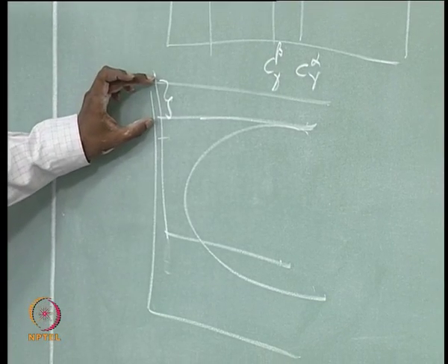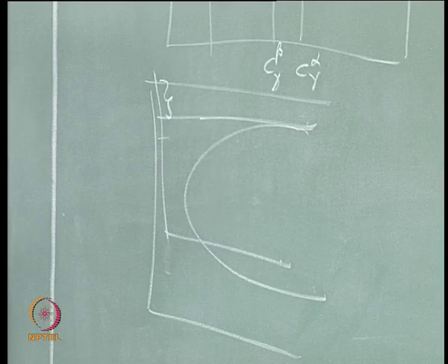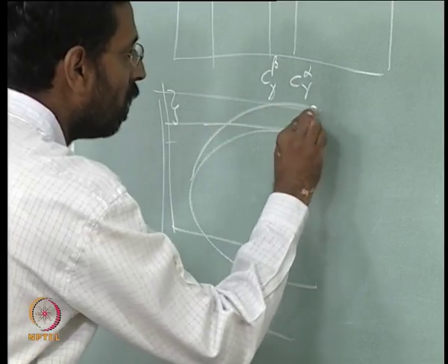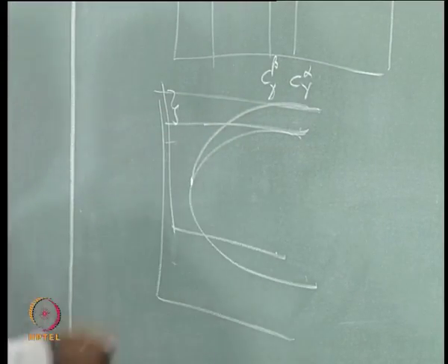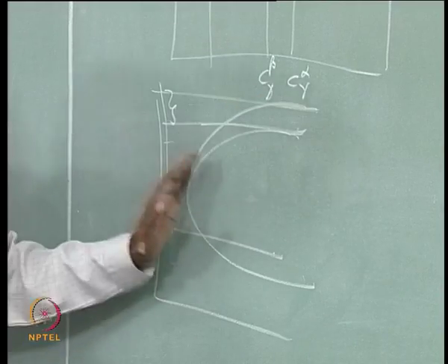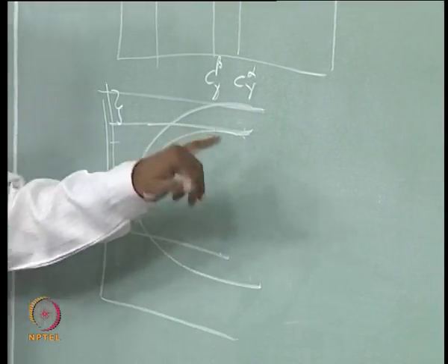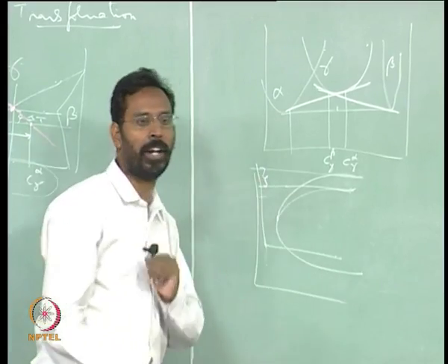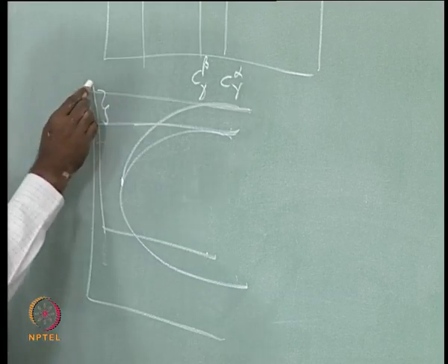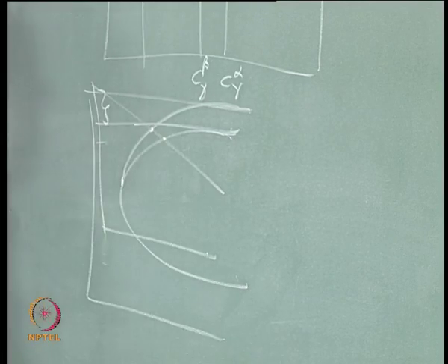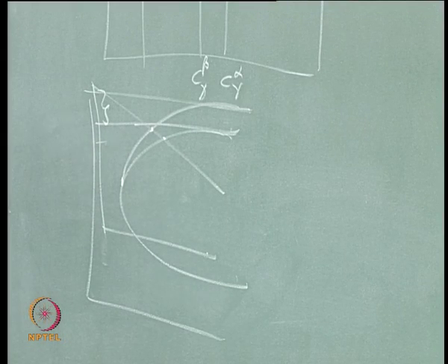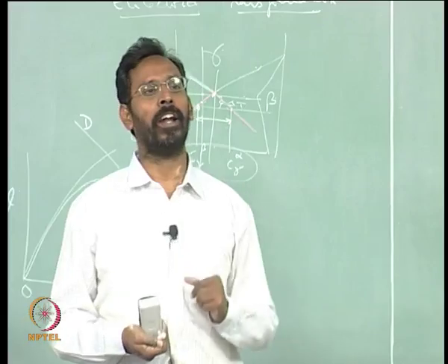So instead of any pro-eutectoid phase coming, straight away you come to a region, and that is why we said if your cooling rate is higher than what is decided by where this pro-eutectoid component reaches the TTT curve of the eutectoid, obviously you will never get a pro-eutectoid phase. If your cooling rate is smaller, then you will cut both these, and you will get a pro-eutectoid phase. Depending on where it is cutting, what is the undercooling that you are achieving, the fineness of the pro-eutectoid phase is going to be decided.